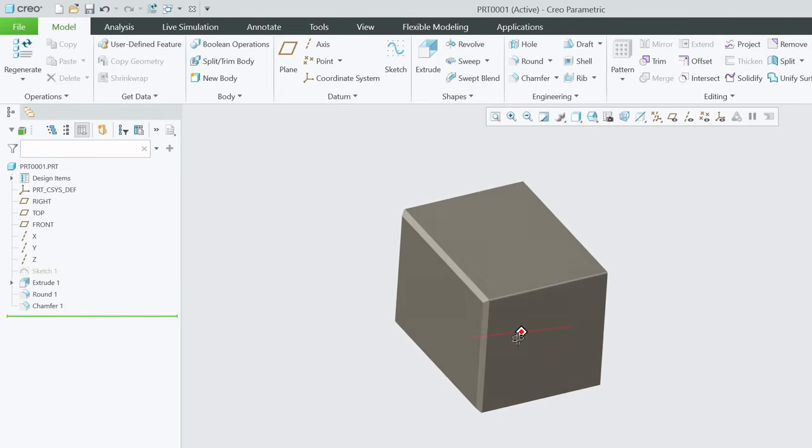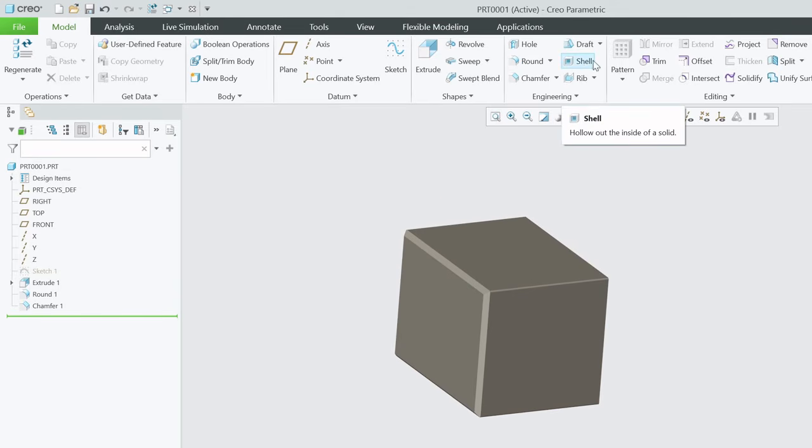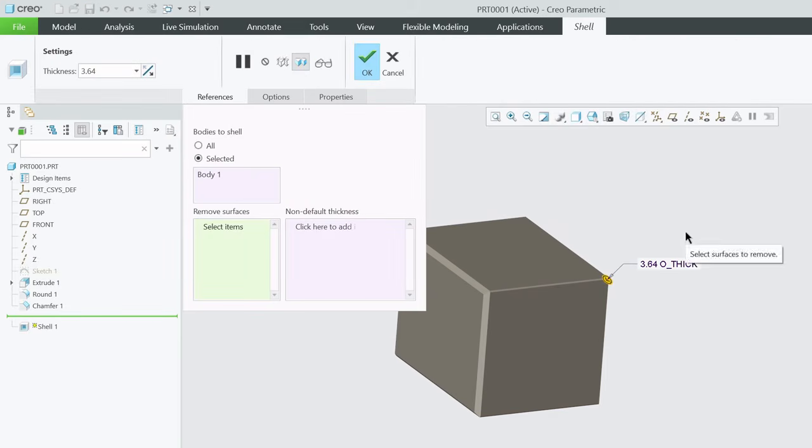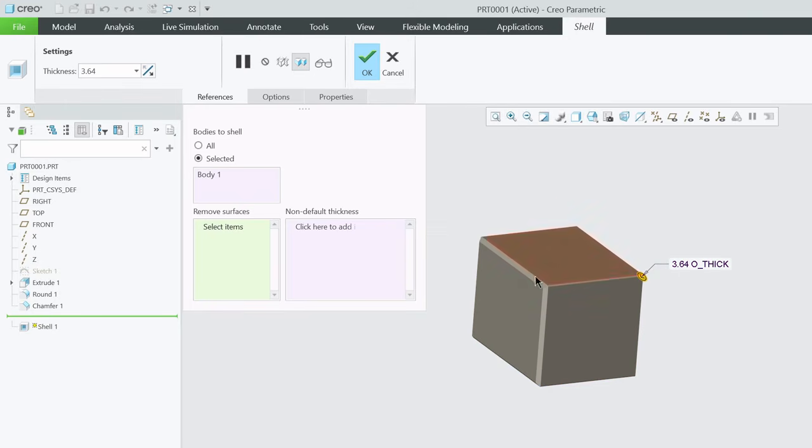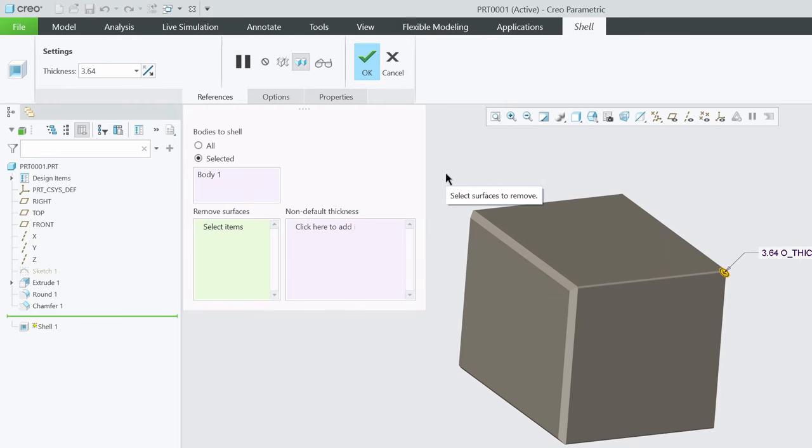Okay, now a nice little feature also that we've got here is called shell. Okay, right there. So we're going to click on shell. So instead of doing like a tube, because now you don't want the opening that side, maybe you want the opening this side, but your extrusion is this way. You know, there's multiple reasons. Once you click your shell, it needs an opening. So you need to pick up a spot where it's going to open. Okay. So if I click there, it's going to give it the opening there. If I click there, I'm going to move the opening there.